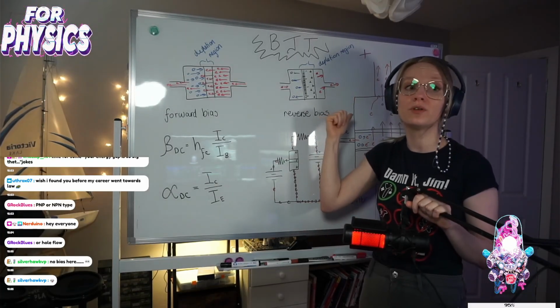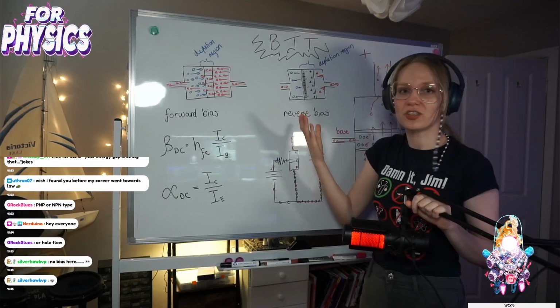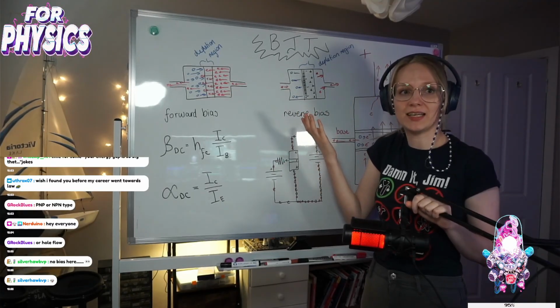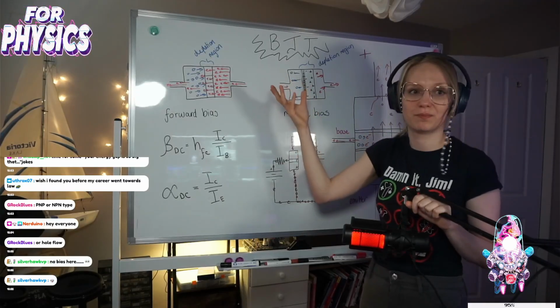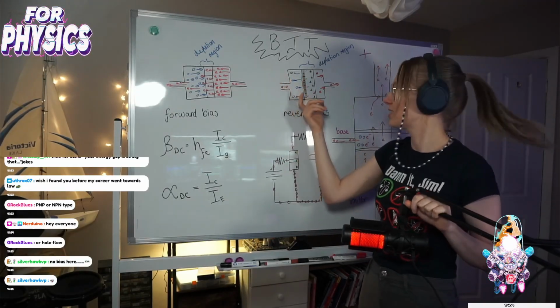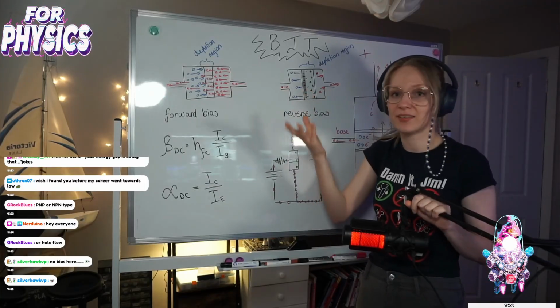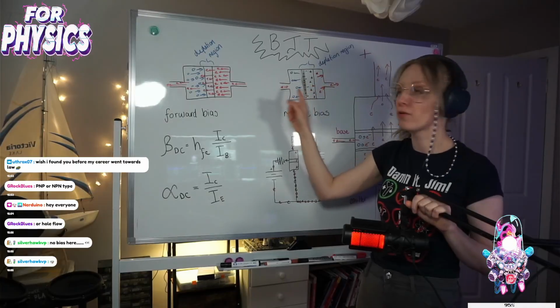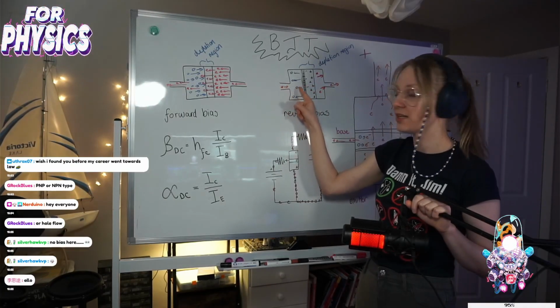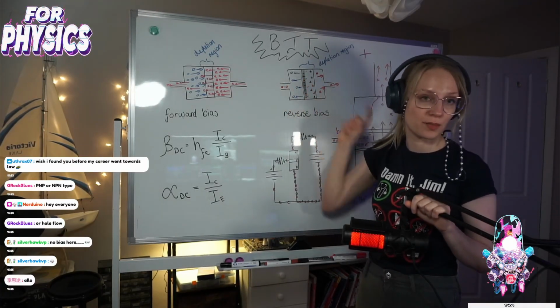Some electrons will move there, but after that, there's not anything left, right? Same idea with the holes going this way. They'll move in this direction, but after they've moved, this depletion region has grown to its maximum size and it won't allow electrons to go through. The electrons cannot jump over. They can't go from here, interact here, and get across this depletion region.